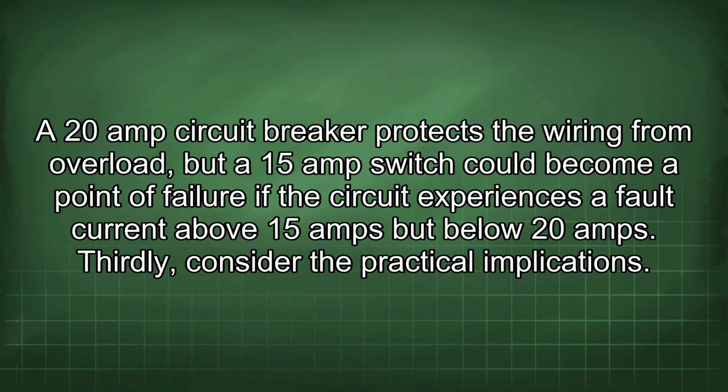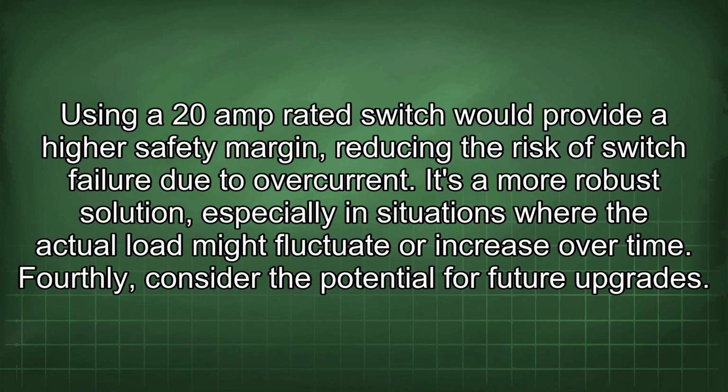Thirdly, consider the practical implications. Using a 20 amp rated switch would provide a higher safety margin, reducing the risk of switch failure due to overcurrent. It's a more robust solution, especially in situations where the actual load might fluctuate or increase over time.